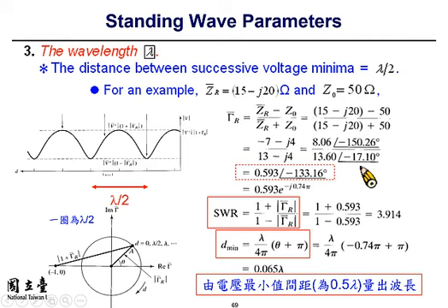And the distance of the voltage minimum can be calculated using known properties. So we know that theta is what? It is minus 133 degrees. So it's located over here. So the d minimum is relatively small. And using this formula, you can calculate the distance as